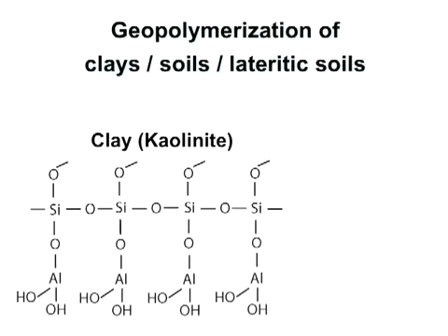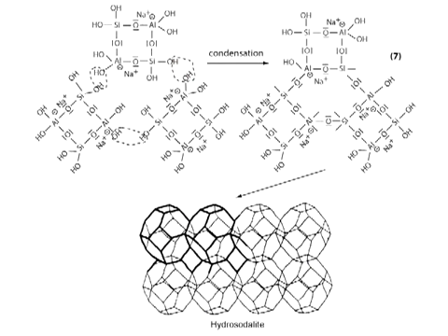It has this structure, and it happens that this very common material is capable of reacting with a very small amount of caustic soda, NaOH, or potassium hydroxide, KOH, in order to provide a three-dimensional polymolecular network of combinations of silico-aluminates that are the analogues of rock-forming minerals.